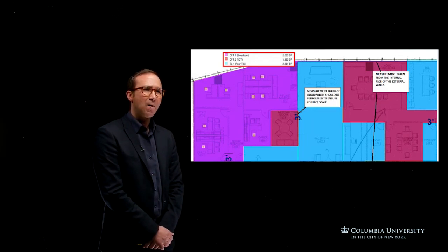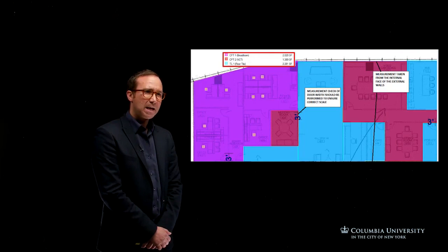When you're actually carrying out the measurement, you measure it from the internal face of the external walls, and you can do it per room basis or per overall area of that floor type. This is from an on-screen takeoff. You can see it quite clearly, and it pulls up your quantities. So the margin of error is less so. The manual way would be a scale rule, and you just mark up your dimension sheet or the document that you're using with the quantities.